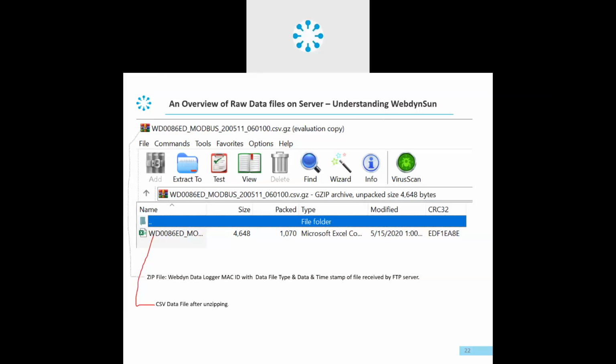Why? When we set up the devices, the data loggers, whenever we need to troubleshoot, we need to log into the data logger remotely. We are sure of the IPs and we can log in directly with that IP. If the static IP is not available and the dynamic is there, we always have to search on the gateway to check which IP was latest assigned to the data logger. But the Datalogger is flexible to work on both dynamic and static. Static is always preferable.